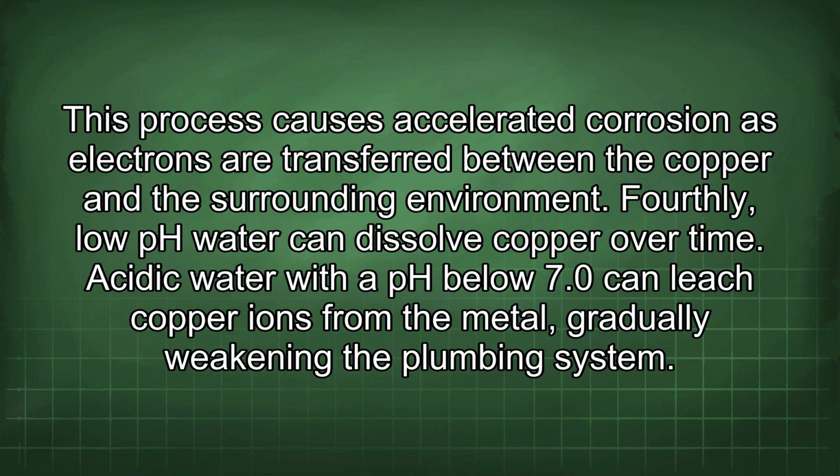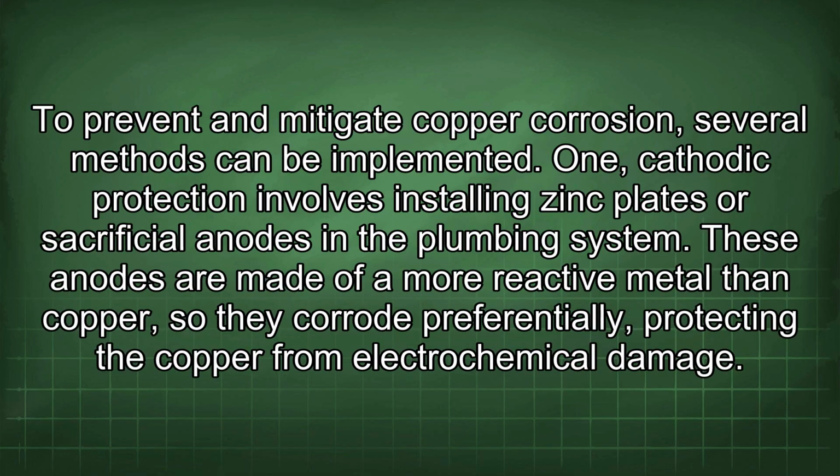Fourthly, low pH water can dissolve copper over time. Acidic water with a pH below 7.0 can leach copper ions from the metal, gradually weakening the plumbing system. To prevent and mitigate copper corrosion, several methods can be implemented.